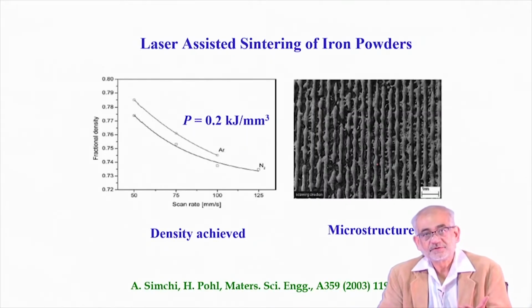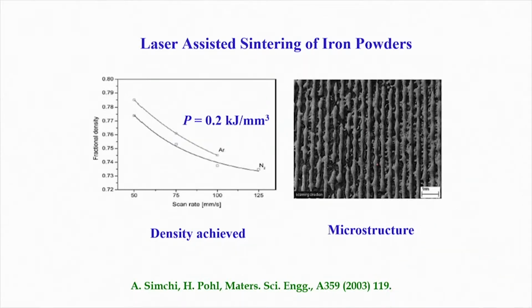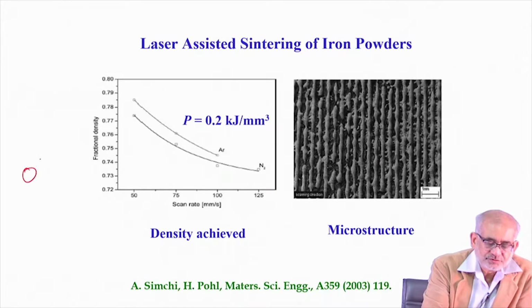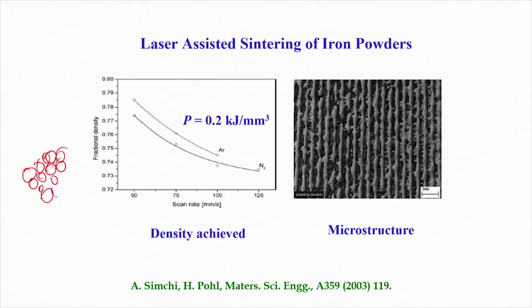Another form of material processing could be sintering. When you are dealing with powders or small objects, I mean particulates, you need to sinter them, join them together. Usually this could be powder masses of either similar or various sizes. So you can have small or big and so on, all kinds of possibilities. Joining will essentially depend upon creation of a temporary diffusion bond, so that electrons can flow across.